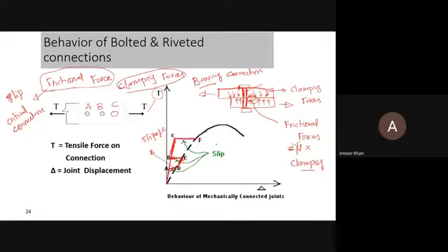देखिए पहले क्या होता है कि frictional force resist करती है. So if the frictional force resists the applied loading, this type of connection we call slip critical connections. There is no slip permitted, but जैसी slip खत्म होती है, the fastener gets engaged with the plate. So this connection becomes a bearing type connection. Bearing type connection का क्या मतलब है कि the load is resisted by the contact of this fastener with this plate. Okay, is that clear?